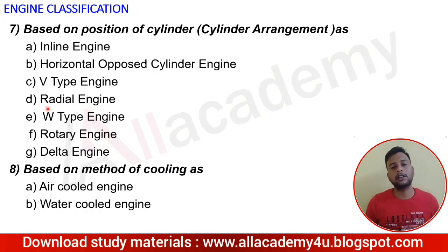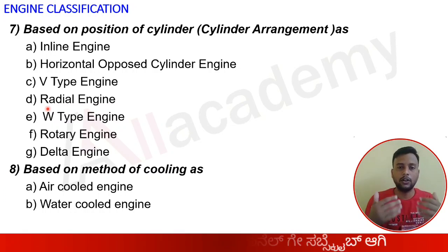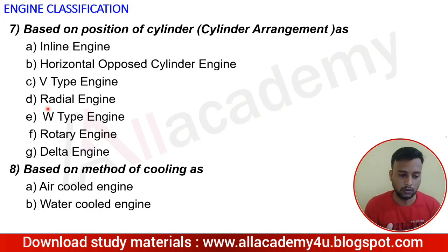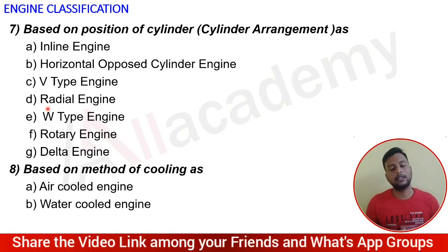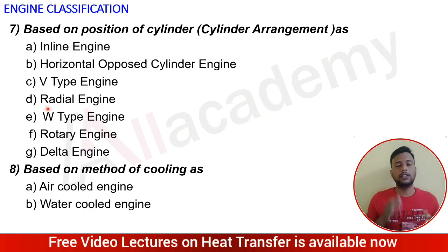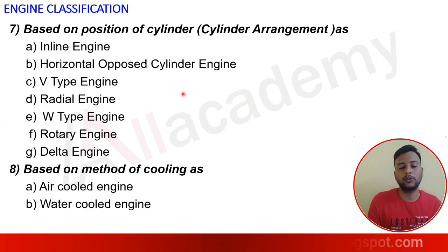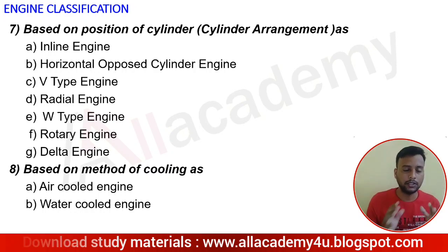Air cooled engines are what we see in the old two-wheelers. The best example is a Splendor vehicle. Just below your petrol tank there is an engine, and there is no cooling system other than the natural air flowing past when the vehicle is moving. So the engine is cooled. And in water or liquid cooled engines, we use separate coolants to absorb the heat generated in the engine, and that reduces the temperature of the engine. Hope that is clear. So these are the classifications of engines that we have studied in detail, but the classification based on the position of the cylinder we are going to study in detail along with schematic diagrams.